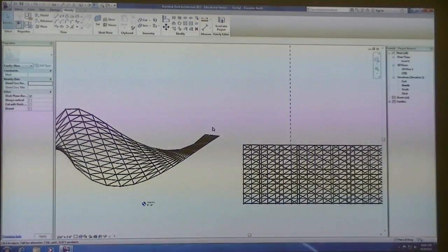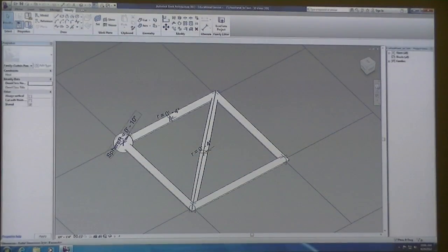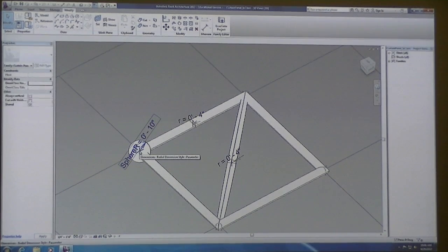So when you're creating any kind of revolve, and that could have been any shape, but it works best with the sphere, you really have to make sure that that vertical line that you're trying to rotate around extends well beyond the endpoints of the curve. Otherwise, it won't make that shape. And you notice when you're done, that line disappears because it was basically a construction line.